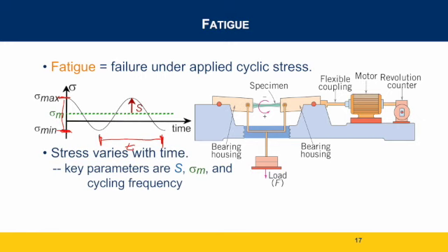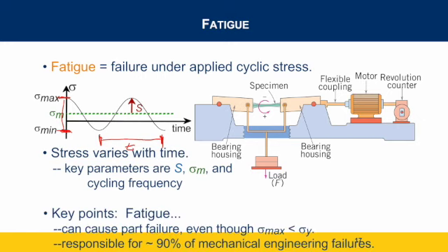So what happens when you fatigue a material? Well, you have a yield strength that's known. You take a sample, put it in an Instron machine, tear it apart, and get a yield strength. Fatigue says that the actual stress the material sees every day can be much lower than the yield strength, but eventually the material can fail at that lower stress. It's important to understand because this happens to about 90% of all the materials that we build every day. They fatigue and break at much lower stresses than they were built to handle.